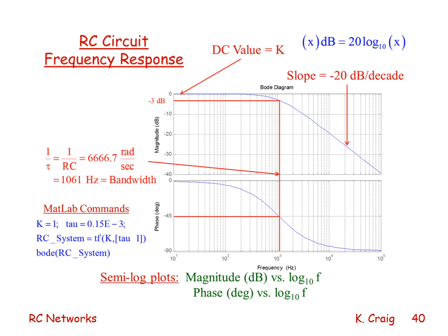So if I were to input a sine wave at varying frequencies, wait for the transient response to die away, so I'm just looking at the steady state response, and I did that for a whole range of frequencies and plotted amplitude ratio, output over input, and phase angle, those two data points for each frequency, I would obtain what we call the frequency response plots, or the Bode plots.